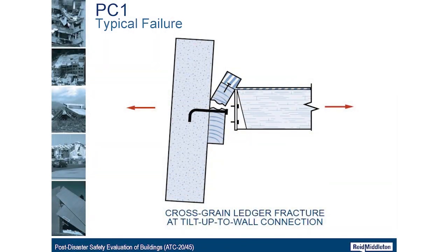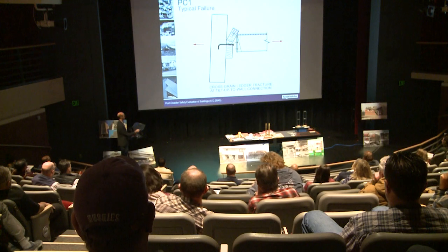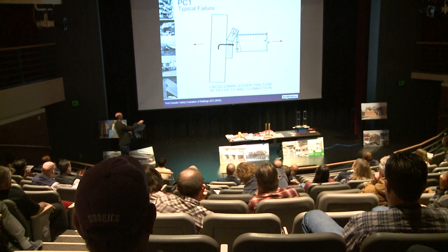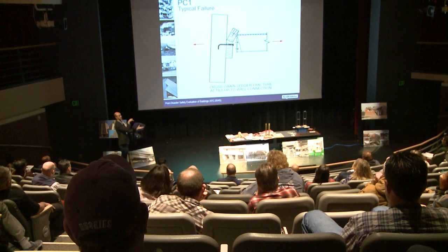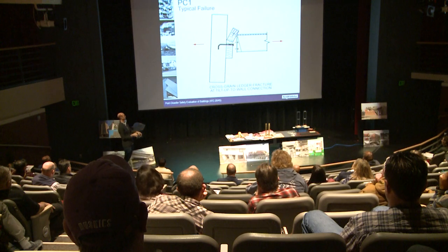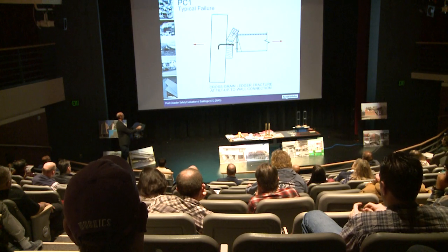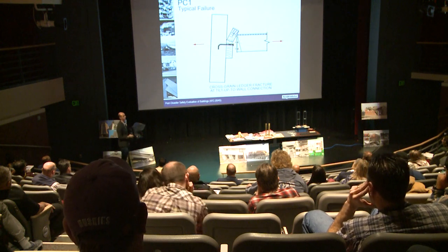And there's this occurrence that we discovered, particularly in buildings constructed pre-early 90s, I believe, called cross-grain bending, which means we have this wood ledger beam. Great, we've got it anchored into the exterior concrete wall. We got the wood framing roof tied into it. We got a hanger. We got our plywood sheathing, all good. But as the depiction suggests, you think of the load path, it's really kind of coming from the top, from that sheathing, nailed into the top of it, and it just grabs that ledger beam, and it's very weak across the grain, as you might intuitively expect.